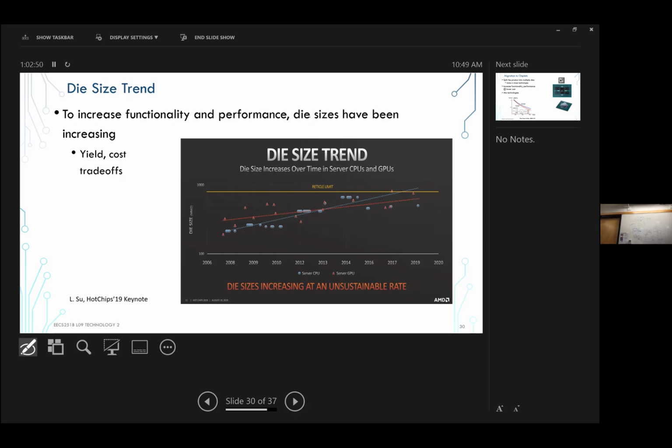What is the largest die size that somebody can make, not us? How big is the die? Not the wafer. It is set by the lithography. One exposure field is 33 by 26 millimeters.